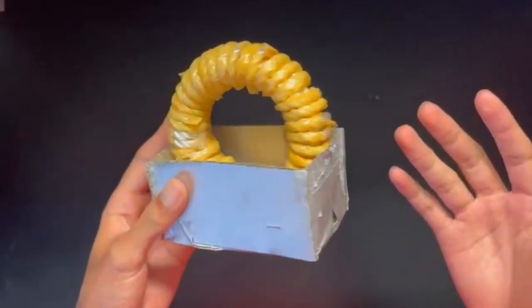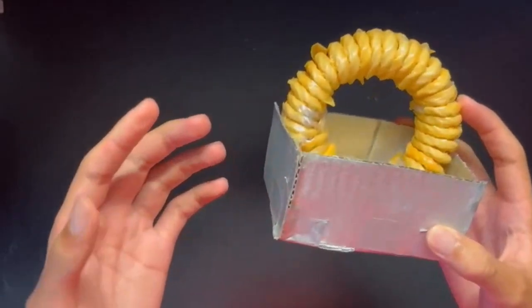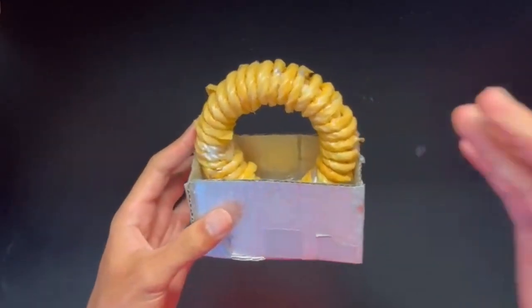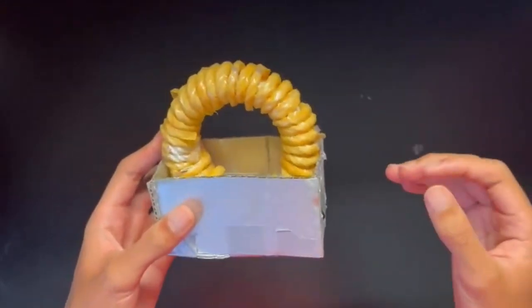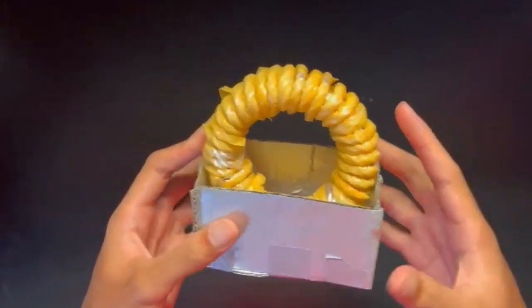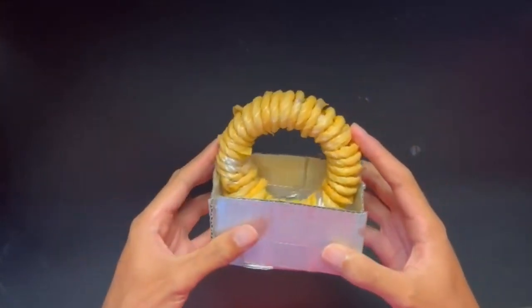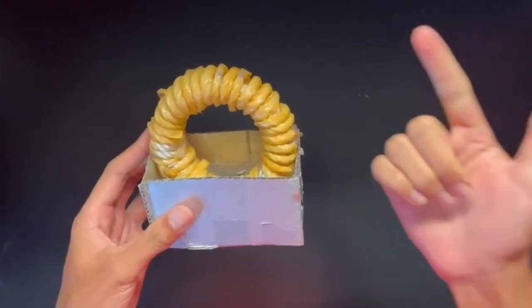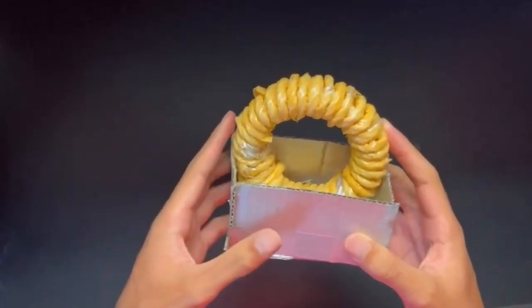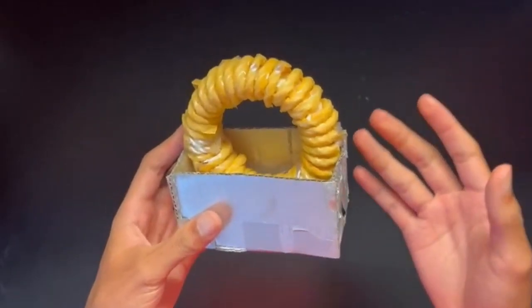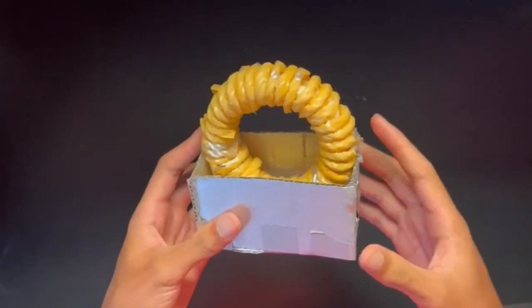When current flows through the coil, a magnetic field is created and guided through the ferrite core. Because ferrite has a very high electrical resistance, eddy current losses are very low. This makes ferrite core suitable for high frequency applications such as phone chargers and power adapters. Although our model does not operate perfectly, this replica will show why ferrite is preferred at high frequency.